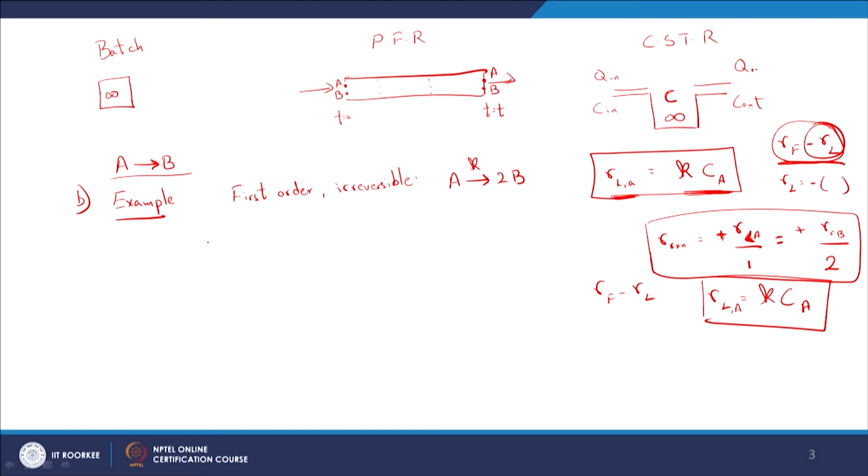So, we are obviously going to apply this on the batch reactor, and it is for mass balance on compound A, and then you know the system boundaries, right. So, the mass balance is, as we know, dCA by dt is equal to rate of formation of A minus the rate of loss of A. This is what we derived for our basic batch reactor a couple of sessions ago, or the last theory session anyway, right.